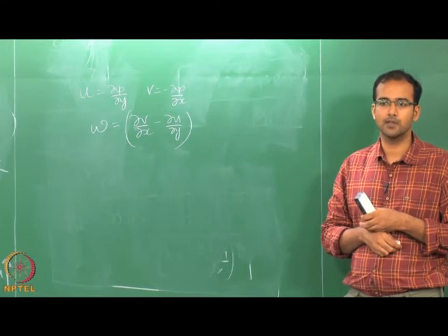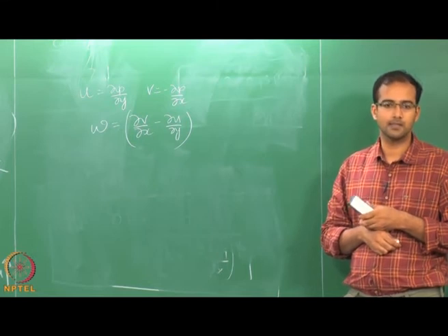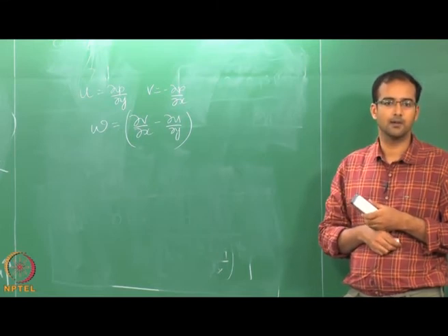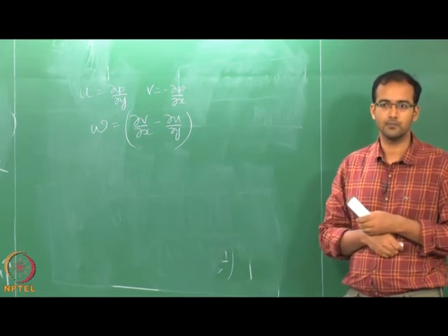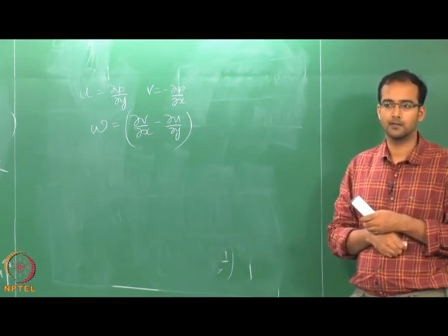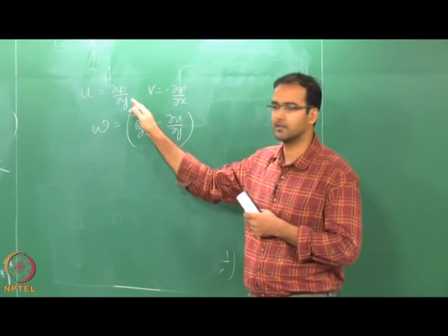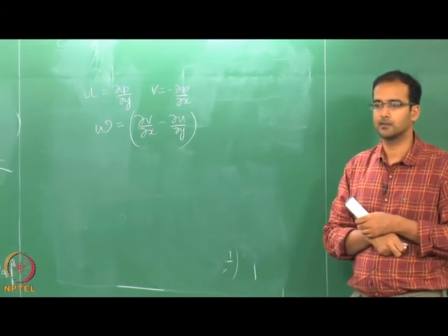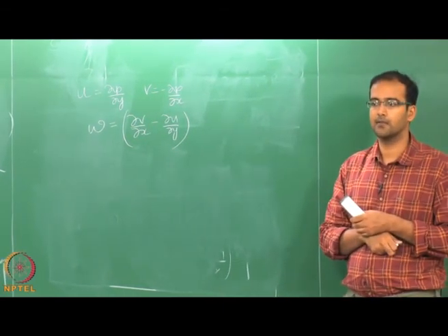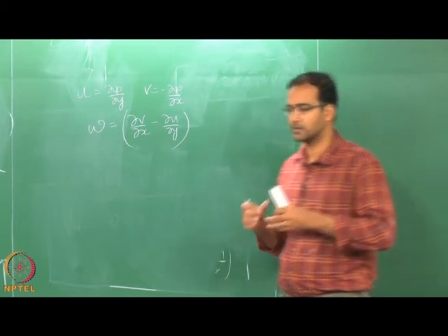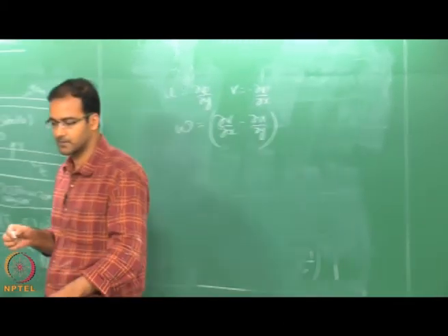So, we can recast these equations in terms of a vorticity equation, and since the stream function satisfies continuity, we will have simple stream function vorticity equations which can be solved.